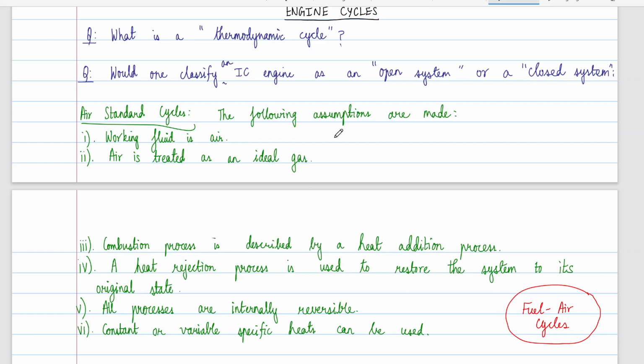and the input shaft runs at an RPM of 7,000 RPM and produces a torque of 110 newton meter. Is this possible, sir, with a 10 kilowatt motor? 10 kilowatt and 110 newton meter of torque and 7,000 RPM. So you just do power matching, no? Yes, sir. But when you use the formula, 2 pi N T by 60, you are saying, is it? I also don't recall the formula off the top of my head.